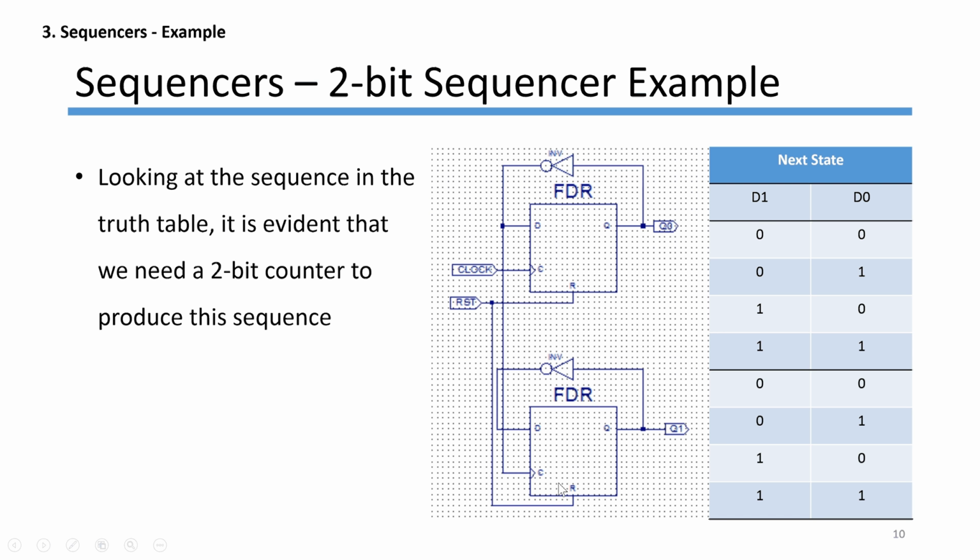In D1, even though it's 0, 0, 1, 1, remember that the flip-flop only gets edge triggered when D0 goes to 0. When D0 is 1, the input to your clock is inverted, meaning it's 0, so you have a low state, and then the next state is a high state, which means a positive edge trigger. So between the second and third sequence, you have a positive edge trigger into your second flip-flop.